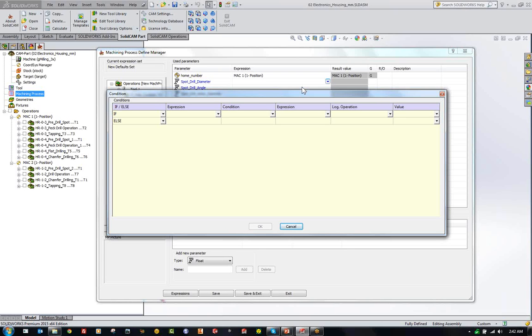You might want to use a 6mm tool for a certain size, an 8mm, a 10mm, 12, and 25, or you might use a 10mm for everything under here, and the next one I'm going to go to is a 16, then a 25. However detailed you want this to get. Myself personally, I like to set these up real close so that if I'm up against a wall, I'm not using a huge spot drill to spot it and tearing my wall up. You're going to have more success with this automatically functioning if you use the spot drill as close to the size you need as you can get. But let's just do something simple here.